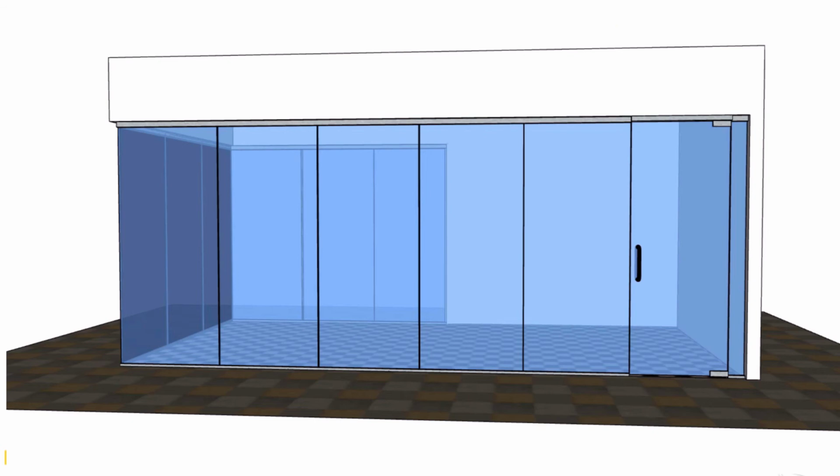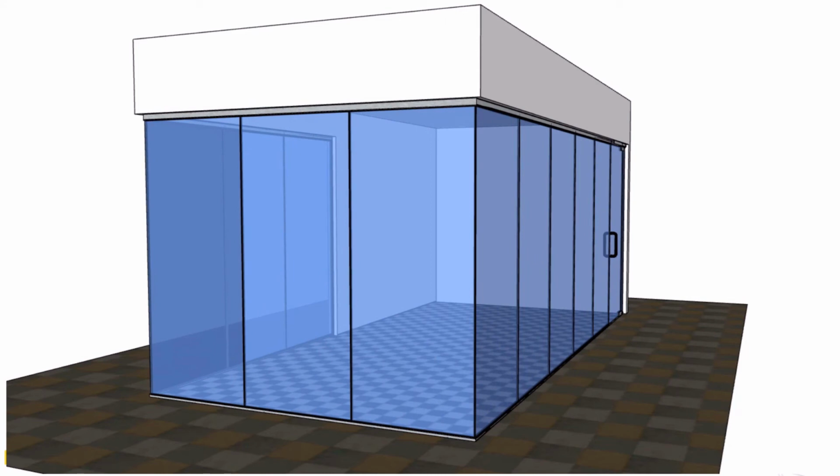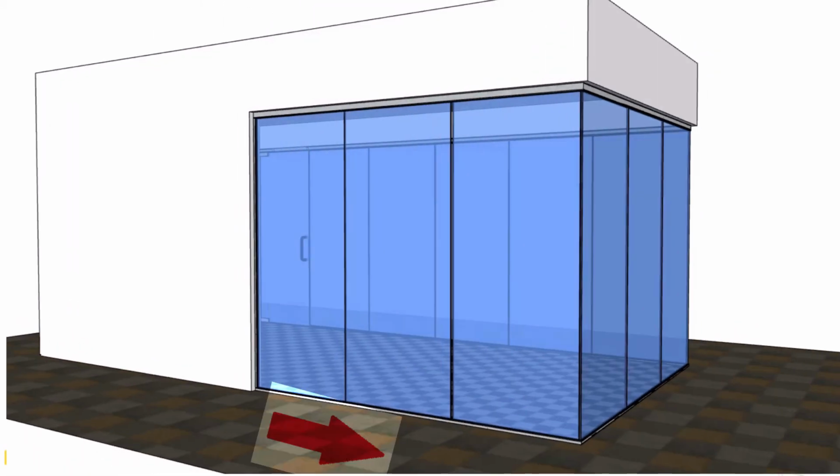Well, not exactly. We're going to be able to see the edge of the returning panel, but our impression from this perspective is going to be less busy because that reflection from the leftmost panel is going to carry through and not be interrupted by a joint and then an adjacent panel's edge. The ordering of these joints is going to depend really on the layout of the building. If, for example, we had a high traffic area here, then the 3 panels might overlap. And if we had a high traffic area over here, then this panel might overlap the adjacent panel.